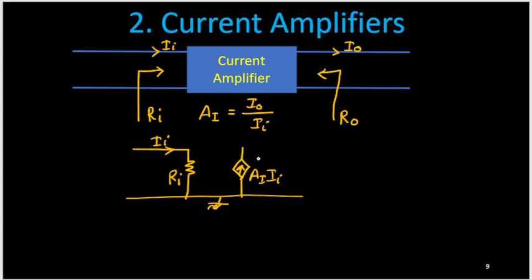So what is this actually? This is a dependent current source depending on this input side current II. So can I call it a current dependent current source? So this I can call a current controlled current source. This is the model, we can use it. Now on this output side I have considered one dependent current source. Now I want to include this output resistance R0. How to include? Whenever you get a current source, the resistance will come across this current source. Okay, the Norton equivalent network you should consider.